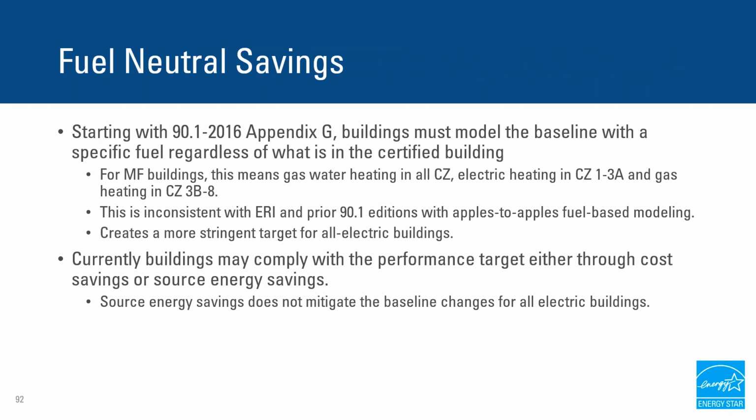And why is this important? So starting with 90.1 2016 Appendix G, buildings needed to model a baseline with a specific fuel regardless of what was in the certified building. So for multifamily buildings, that means gas water heating in all climate zones, electric heating in climate zones 1 through 3A, and gas heating for 3B and up.